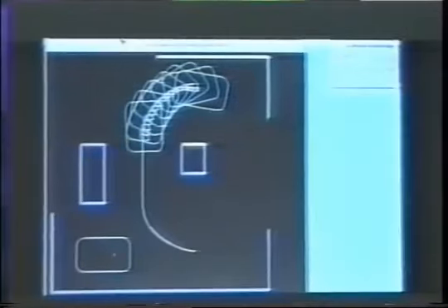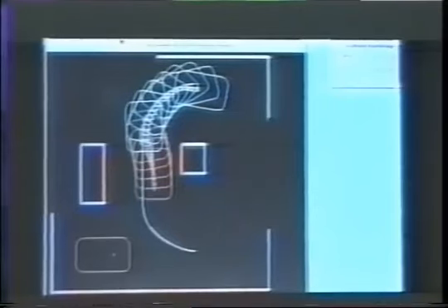We use exteroceptive information provided by polarized sonars in order to compensate for disturbances by convenient closed-loop tasks. The mission is split into 3 paths, each one referenced to some local element. The first part of the movement is marked by blue-colored elements.